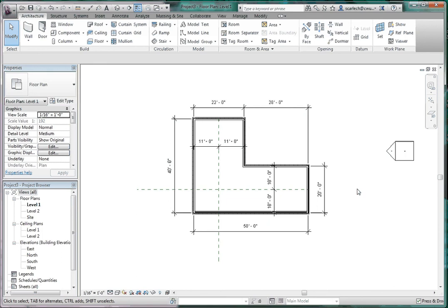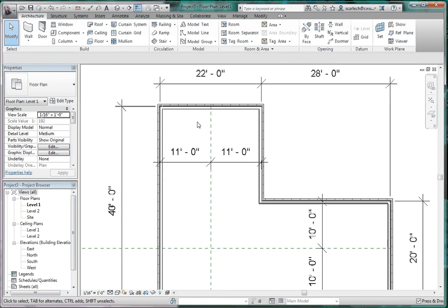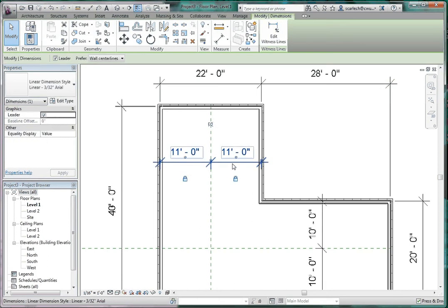Pretty easy. So one thing to keep in mind about the planes is planes don't drive the model. They don't drive the walls, interior or exterior walls of the model. It's the model itself, or the walls, that drive where the planes are going to be. And one advantage of the planes is now, if we want to put a hallway perhaps right down to this building with a front door over here and perhaps rooms on either side, we can do that.